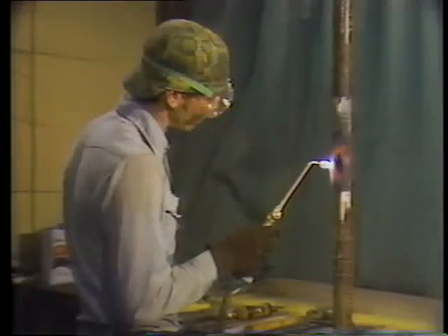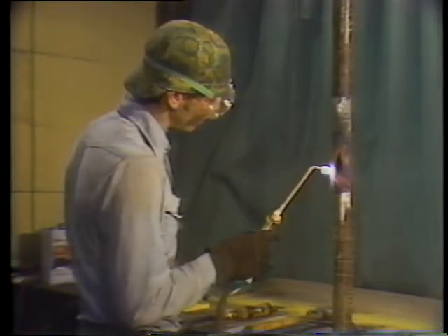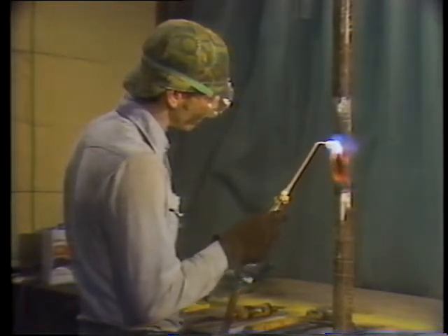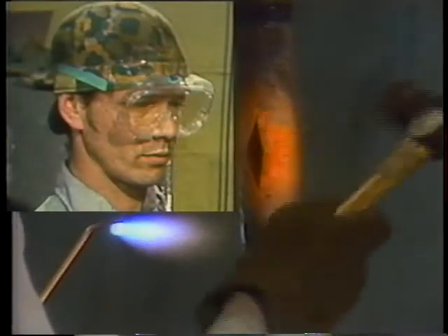The tube should be heated until it's cherry red. If you hold the torch too close to the tube, it will get too hot. The tube should be hot enough to bend, not hot enough to melt. Once the tube has been evenly heated, close the rupture by pounding the tube with a hammer. This forces the edges of the rupture back together. Eye protection must be worn when doing this because fragments of metal might fly off the tube.